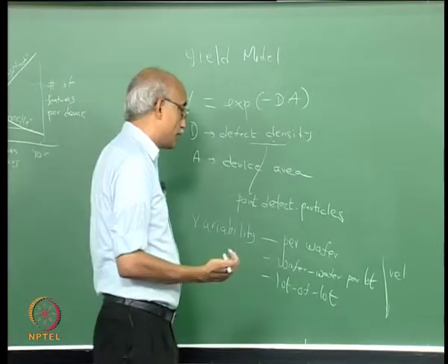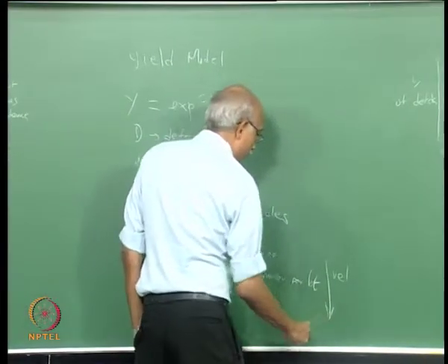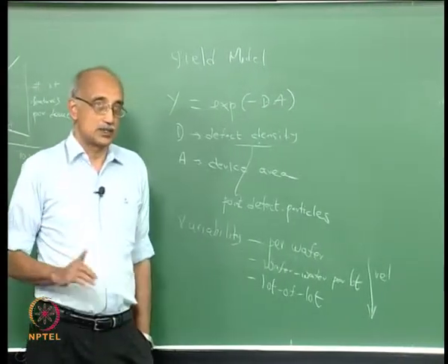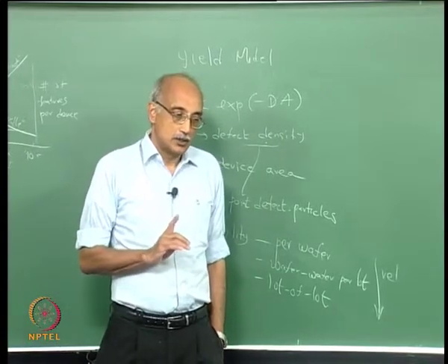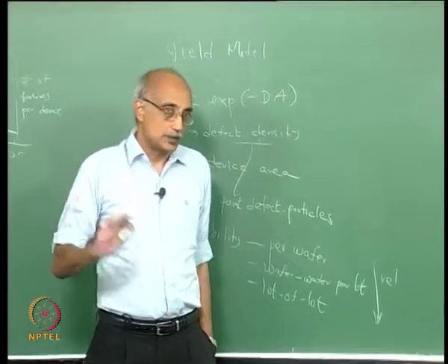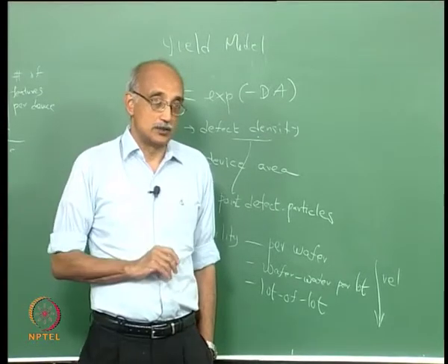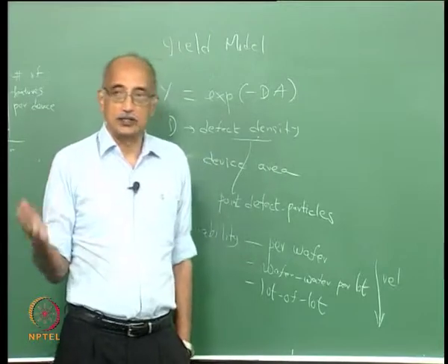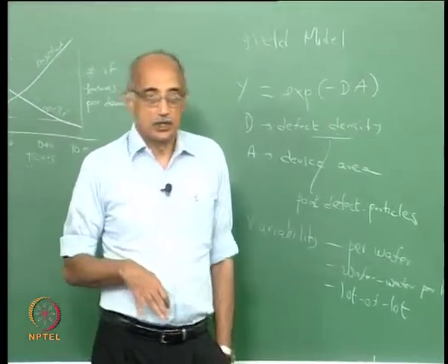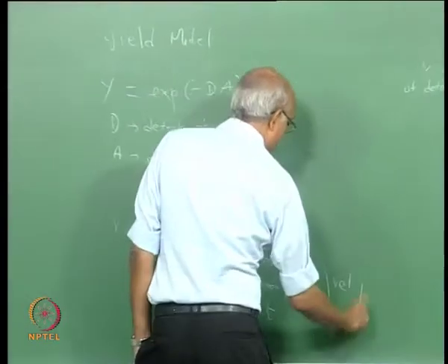Now, that is true for reliability, but for yield that is not necessarily true, because yield essentially means that you are throwing out bad stuff. So, that is good for the field, it protects your customer, but from your process yield viewpoint, the more bad stuff you throw away, the lower is your yield, right. So, yield actually goes the other way.